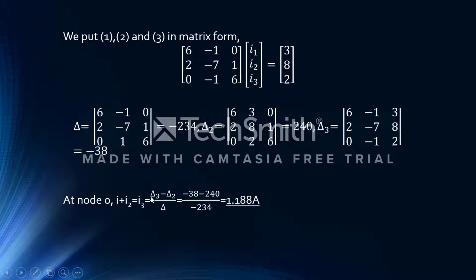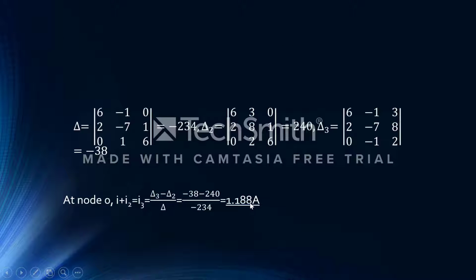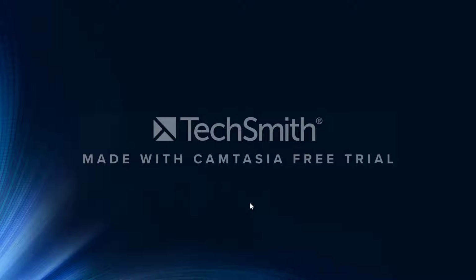So on solving that, I is nothing but I3 minus I2. I3 minus I2 can be written as delta 3 by delta minus delta 2 by delta, which is delta 3 minus delta 2 whole upon delta. So on solving that, we get minus 38 minus 240 divided by minus 234. We get 1.188 ampere. And that's it. End of the slide. And hope you all would have understood something from this.